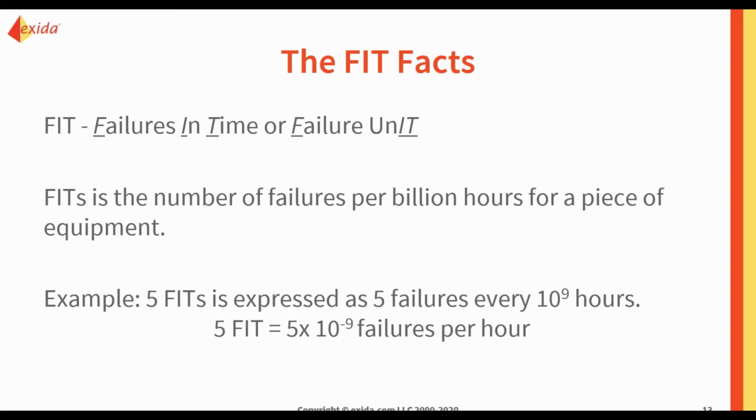It is mentioned, as I said, both in IEC 61508 and IEC 61511, and its preferred unit of measurement is usually 10 to the negative 9 hours. That's per billion hours. So when you hear people talk about failure rates they get from a certificate or from an FMEDA, a failure mode effect and diagnostic analysis report, they are generally speaking in terms of FITs.